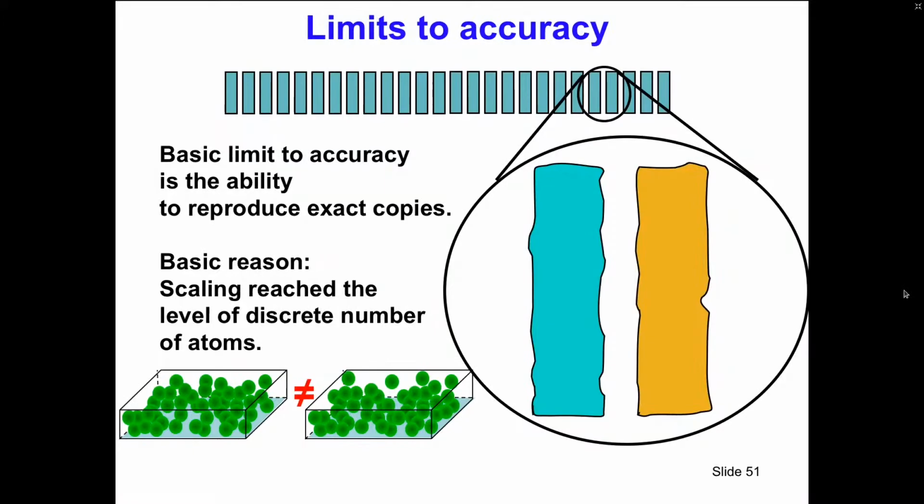If I want to build in an A to D converter equal elements, equal resistors, equal capacitors, equal currents, then in the end I will end up with something like this as a pattern. This could be resistors, capacitors, current sources, or whatever more. And the question is, what limits the accuracy of such a structure? So this is intentionally all the same, but it turns out that it is not.